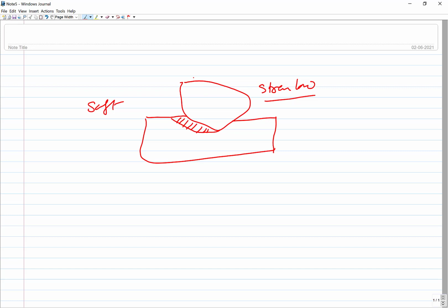So on the other hand, if a large size abrasive is used with the hard metal, under identical conditions the stress will be high. Okay, if this material is hard, the stresses will be high, and under the high stress abrasives may break.